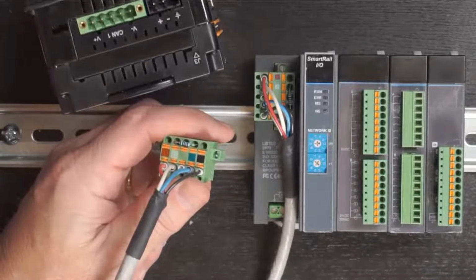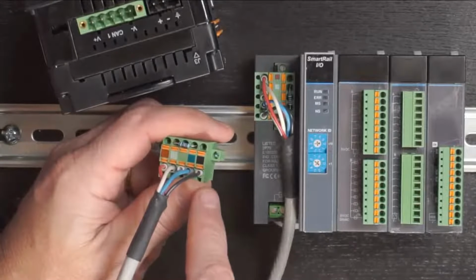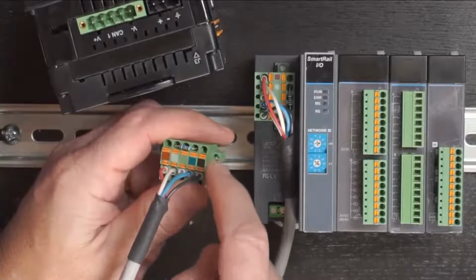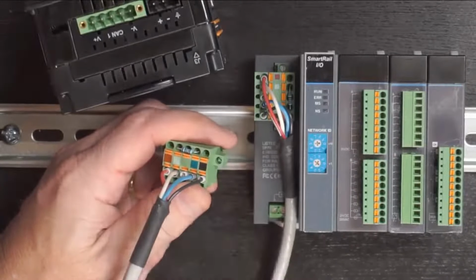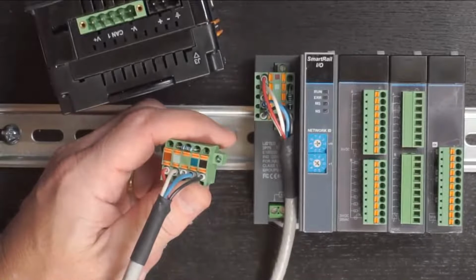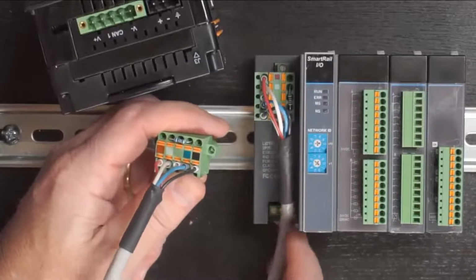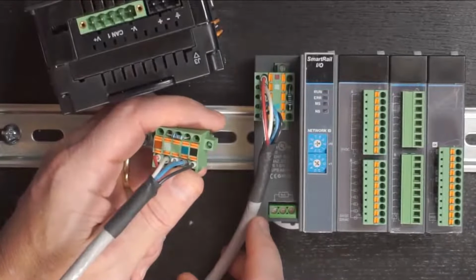And the benefit of the double CAN cable is you have a different set of contacts for network in and network out. And if you're on the end of the network, instead of network out, for instance, you have a dedicated spot you can land your termination resistor between the blue and the white conductors. And because these are the only 2 things on the network, I'm doing the same thing at both ends.